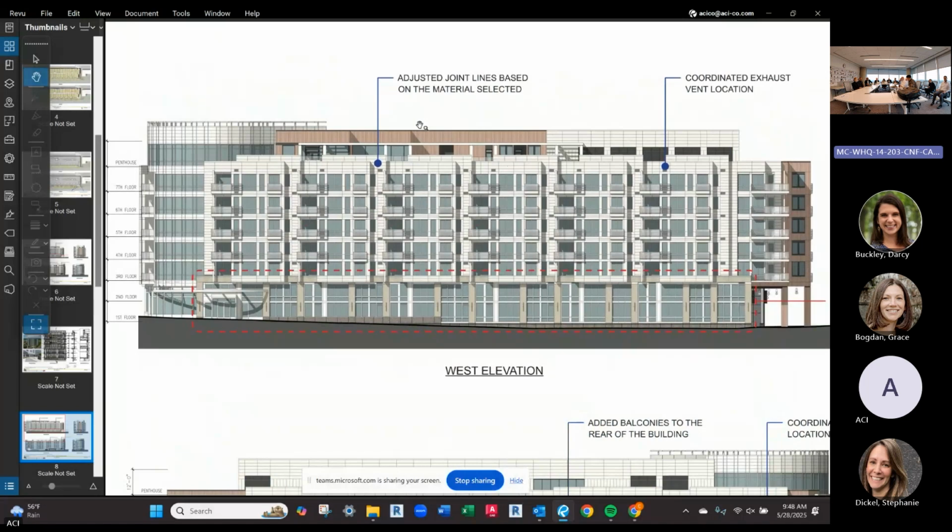We're not much fond of that, and I think it will serve the building better, albeit a little more expensive. We would like to install this as a rain screen system. And as you know, that also has some pros and cons. The pros are that you have to provide exterior continuous insulation. You get your thermal insulative values on that skin, and this is just an exterior surface treatment, and it can be repaired easily if it's damaged. So that's a positive thing, and I know that the ownership is concerned about that. They own a number of buildings, and that's one of their.